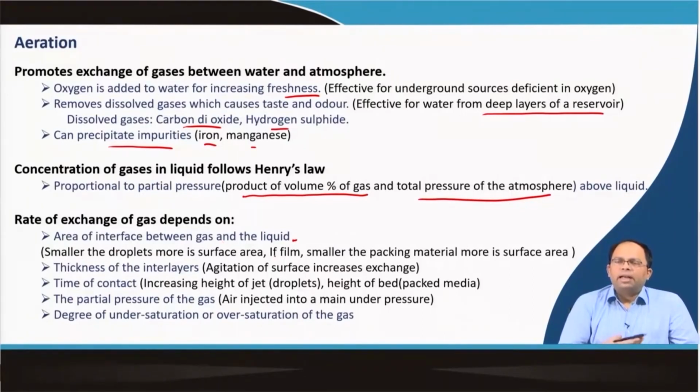Or the water can be applied in a film, that means as a layer, usually over a packing material or filter media. It could be certain kinds of activated carbon or coke, or even brick bats. The smaller the packing material, the more the surface area for that film, and that will increase the exchange as well. Then the thickness of the interlayers, that is agitation of the surface, also increases the exchange.